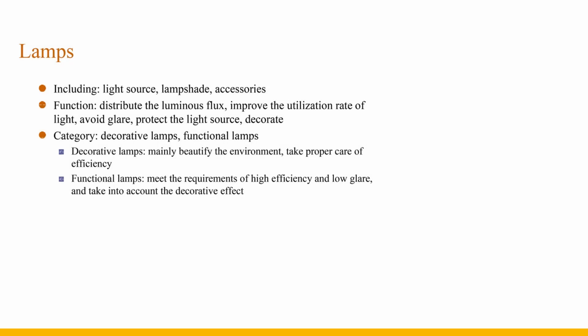There are three light characteristics of luminaires: photometric curve, shading angle, and luminaire efficiency. The luminous intensity distribution curve of a light source or lamp in all directions in space is called the photometric curve. Plotted on a plane in polar coordinates, each point on the photometric curve represents the luminous intensity of the luminaire in that direction. Photometric curves are usually drawn with a luminous flux of 1000 lumens from a light source.